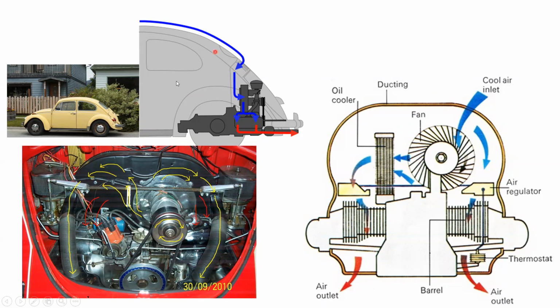Because of that, even at low temperatures and low speed, the engine is getting cooling from this fan. The fan is directly bolted to the alternator itself. Actually, it's a generator, not an alternator, because this is a very old engine. This is what used to generate the electricity.